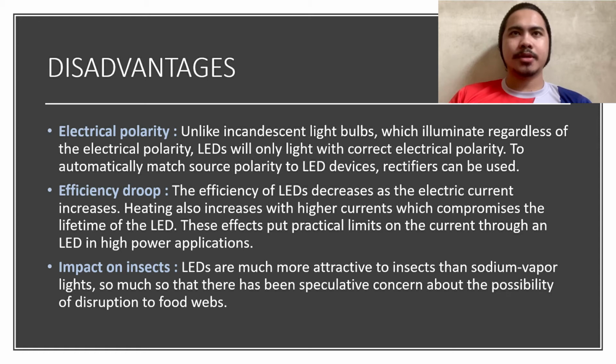Okay, for electrical polarity, unlike incandescent light bulbs, which are regardless of electrical polarity, an LED will only light with correct electrical polarity. To automatically match source polarity to the LED device, rectifiers can be used.